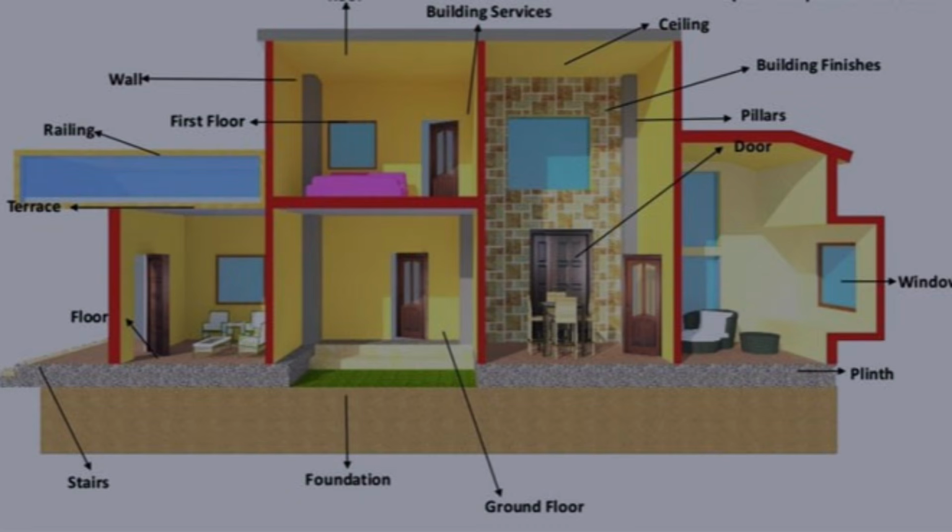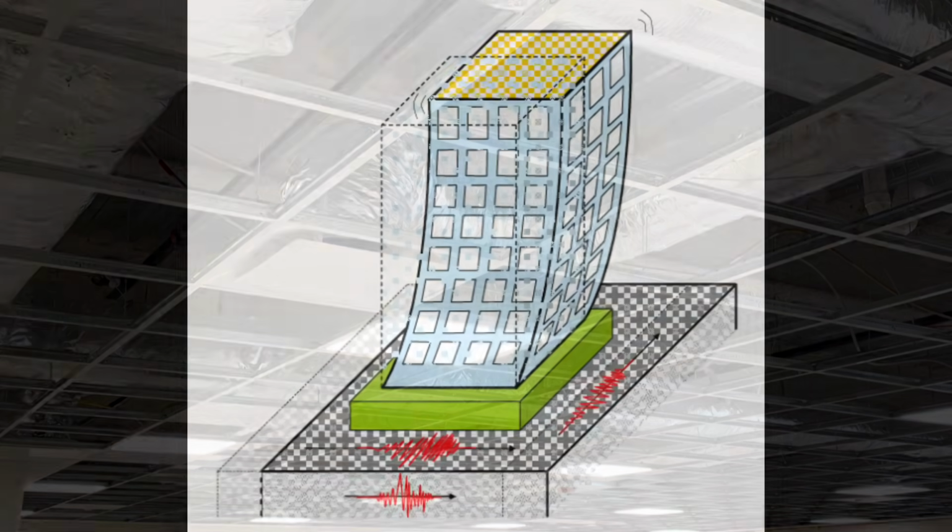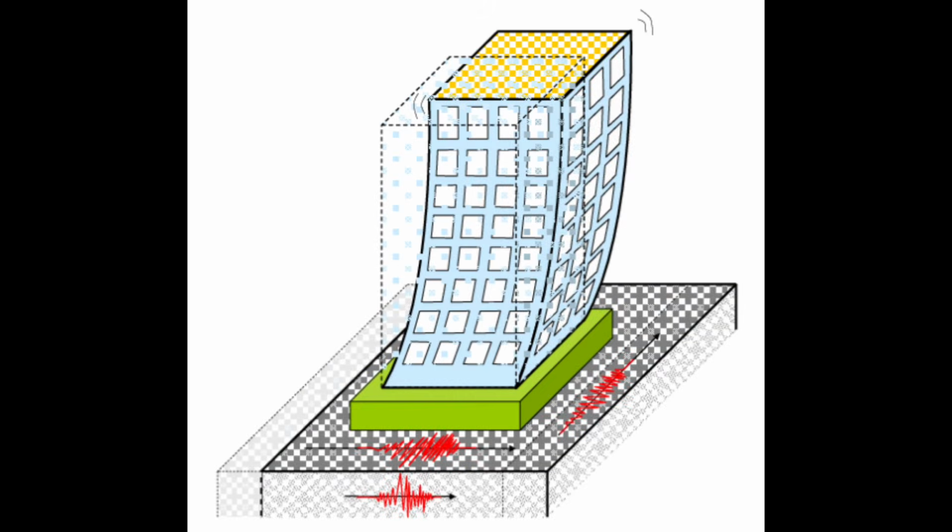So, IS 1893-2025 clearly states that AEUs must be seismically restrained, designed for appropriate seismic forces, and anchored properly. This includes false ceilings, facades, HVAC systems, water tanks, and electrical panels. So, friends, the message is clear here. A structure is not earthquake safe unless its non structural components are also safe.